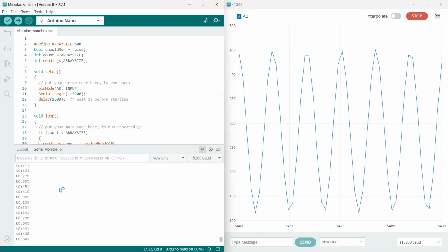And what I can do is scroll through these values, and if I really wanted to determine what the apparent sample rate is, I could look for the minimum, which would be, say, down here on one cycle, and then watch when it goes to a maximum and then back to a minimum. That gives me at least a crude idea of what the actual sample rate is.